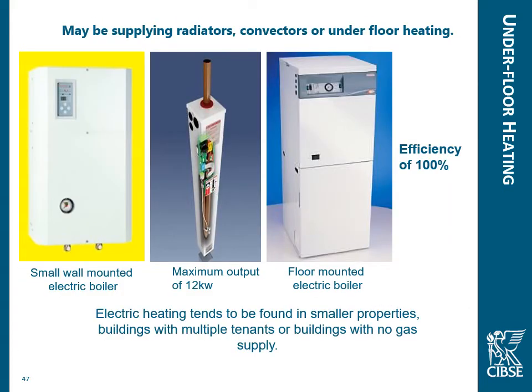Now, what about electric heating in our building? Well, generally that's quite expensive, and electric heating has always had bad press. Electric heating is always 100% efficient. Whatever we put in is what we get out. We put 1 kilowatt in, we get 1 kilowatt out. Now, electric was always considered bad because it wasn't a problem with the electric heating, it's a problem with the buildings it was put in.